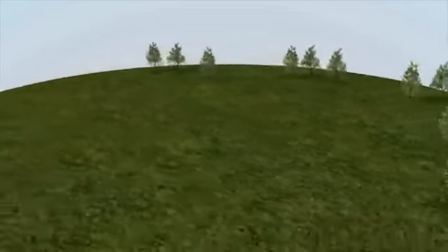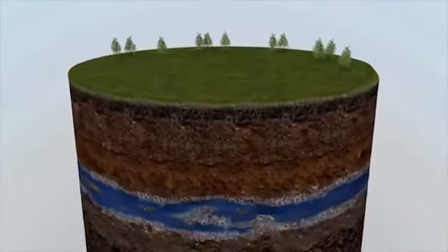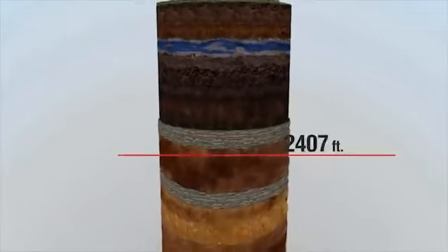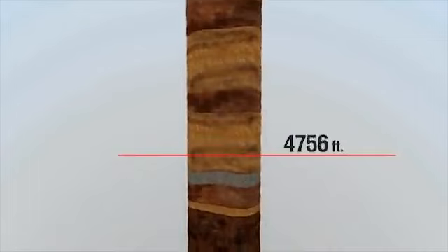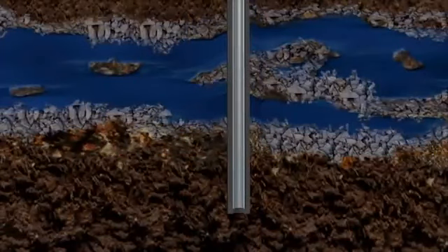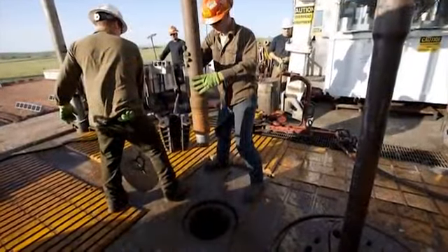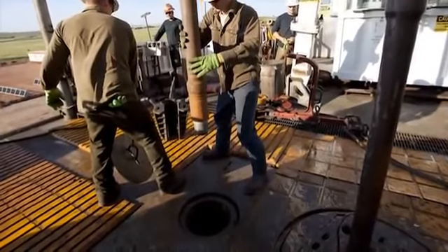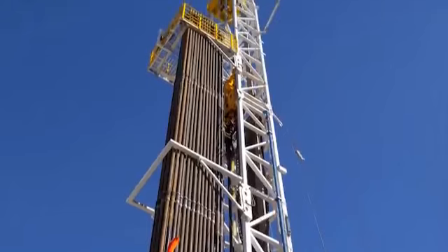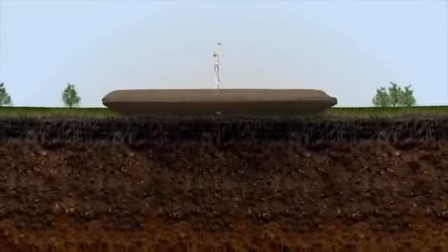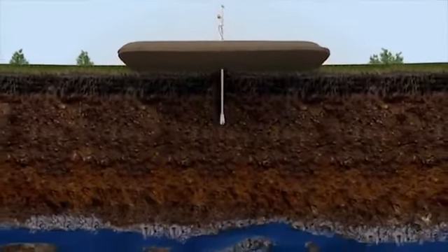Shale reservoirs are usually 1 mile or more below the surface, well below any underground source of drinking water, which is typically no more than 300 to 1,000 feet below the surface. Additionally, steel pipes, called casing, cemented in place, provide a multi-layered barrier to protect freshwater aquifers. During the past 60 years, the oil and gas industry has conducted fracture stimulations in over 1 million wells worldwide. The initial steps are the same as for any conventional well.